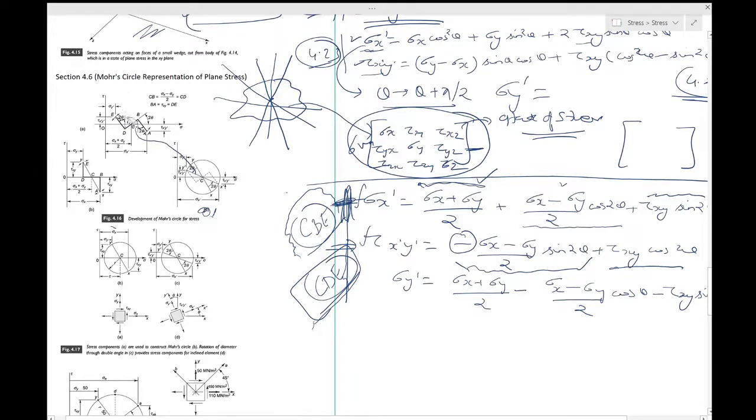That's where we had left off. In the x dash y dash situation, there was no requirement for theta to be 0 degrees, and that's why we call them the transformed stress components, and clearly x and y are the original untransformed stress components. So that's how you can see this diagram, 4.16C. We'll continue with the discussions given in the textbook ahead.